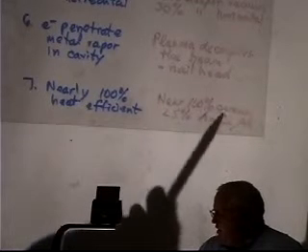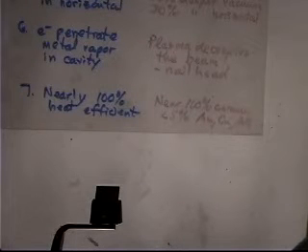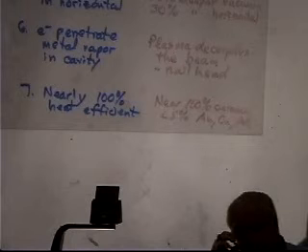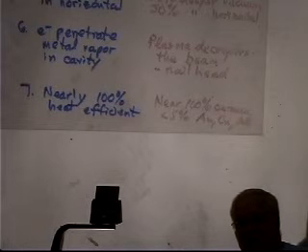For the laser, this is nearly 100% efficient on ceramics, although it may penetrate, since ceramics may be somewhat transparent, so it may not be true surface heating. But on very reflective materials, such as gold, copper, and aluminum, absorption can be less than 5%, because these are very good mirrors. They reflect light. In fact, if I'm going to use mirrors to transmit a high power laser beam, the high power mirrors are made out of copper because it has good thermal conductivity and will carry the heat away, and then they gold plate the surface.